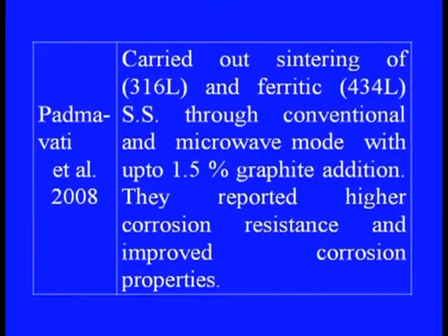Then Padmavati and his research group carried out sintering of 316L stainless steel and ferritic stainless steel, that is 434L, through conventional and microwave mode of heating with 1.5% graphite addition. They have found higher corrosion resistance and improved corrosion properties with these microwave sintered products.